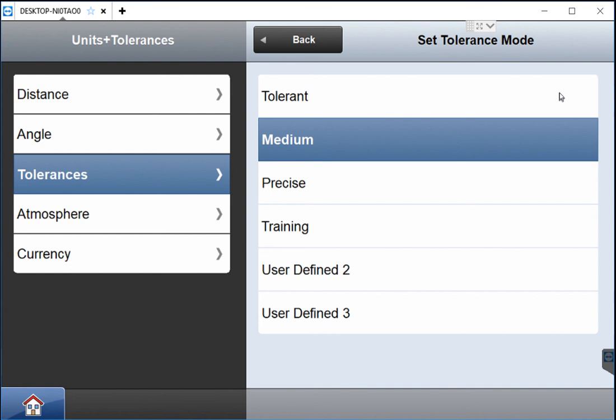If you have a reason for laying out a point away from the designed coordinate provided by the office, and you know for a fact that where you laid out the point is where it should be, the color won't be a problem. If you feel you have laid out the point correctly, though, and you are still receiving the error message and a yellow point, you should check for the same issues I brought up concerning the setup. A green point upon storing means you are good both horizontally and vertically. In general, your tolerance setting should be set to medium, and you shouldn't have to change it once it's set.